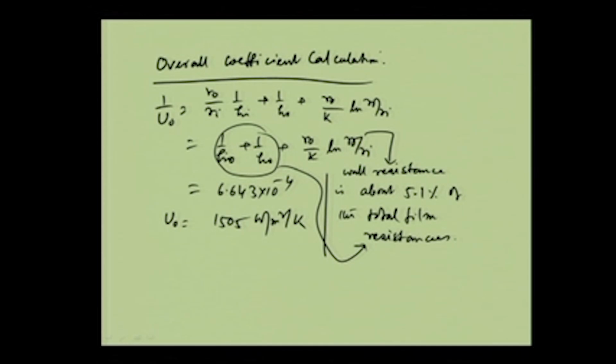Now what you have to find out is that RD we will take, for two different fluids, as 0.000172 for one side fluid plus 0.000088 for the other side fluid. So this is total becoming actually 0.000258 meter square per Kelvin per watt.